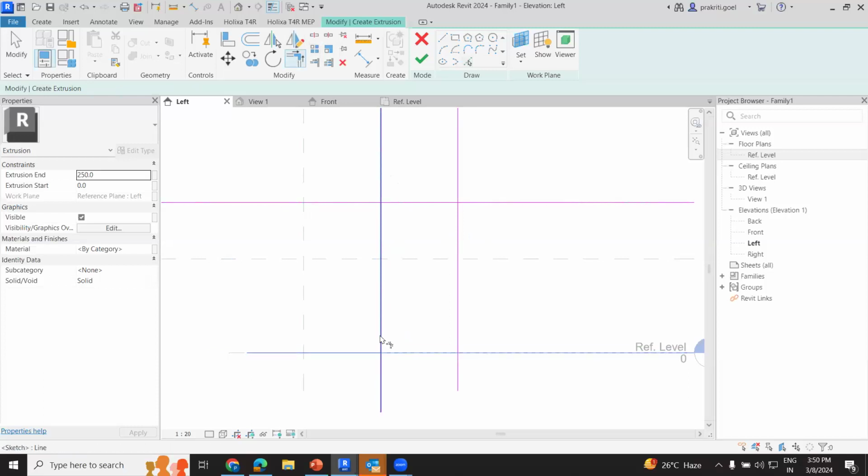right? And let's say if you have some curvature at the edges or maybe chamfering, and certain dimensions are fixed, you don't want to change those dimensions. Those are fixed, right? So what you can do, you can provide dimensions inside the sketch. It is just like Ramneet ma'am said, certain families become heavier, right? So our motive needs to be to create a light family. More reference planes can make your family heavier.